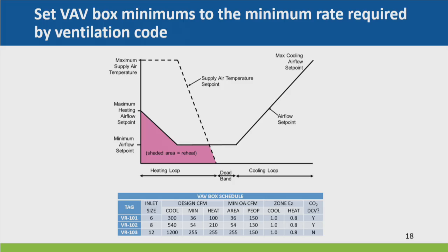It's only the ventilation rate required by the zones that are there. And then for those familiar with Standard 62, our ventilation effectiveness is a function of the supply air temperature. So if we have warm air, it tends to stratify, doesn't mix as well, and so I need to account for that. And for cooling, it works great, so I don't have to. And then both 90.1 and Title 24 have CO2 demand control ventilation requirements for densely occupied space, like the space here, where we can reset the ventilation.